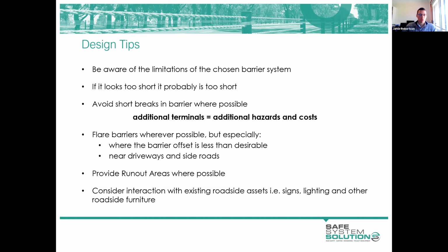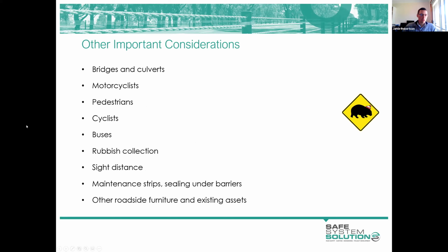Take all the measurements that you can, particularly hinge point offsets, batter slopes. Think about the window within which you might be able to install a barrier, and what is the scope to do further earthworks if you decide that is something you might want to do. There are lots more things that you need to be mindful of. Sometimes it really does depend on your specific situation.